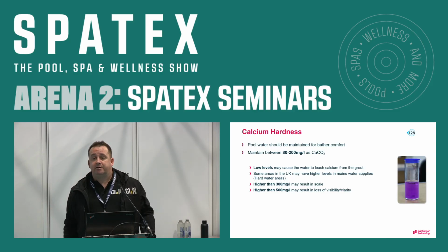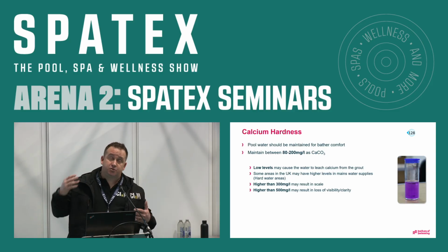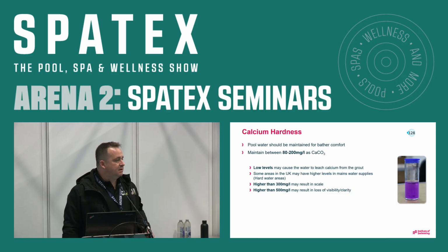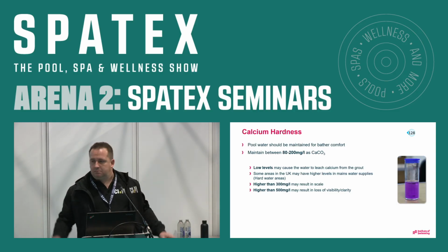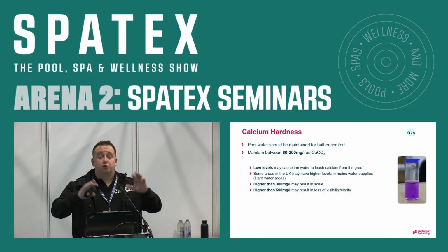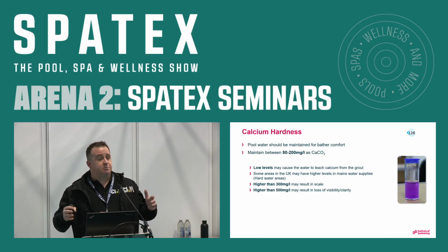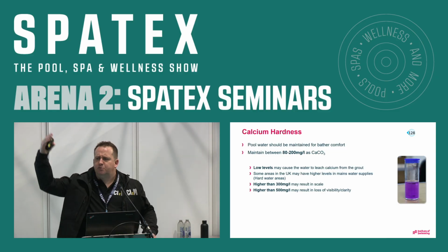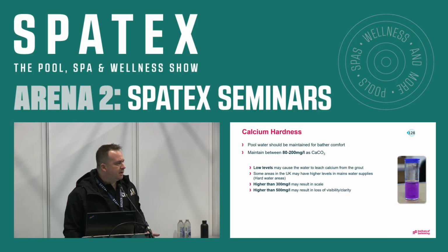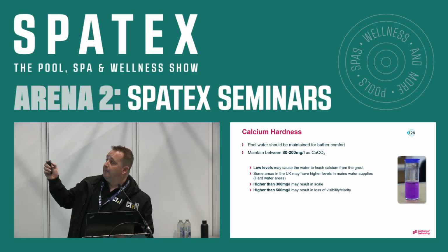And in hard water areas, the only thing we do to try and control it is minimize our use of calcium-based disinfectants, okay? Now, that's not a straight line because there are numerous pools I know of that have had calcium-based systems installed and they work very well in a hard water area, but it just needs a little bit of extra technical playing around. But as a rule, we don't use calcium in hard water areas, we use it in the soft water areas. So Scotland, North England, West Wales, Devon and Cornwall will nearly all run on calcium hypochlorite, or HH as we commonly know it.